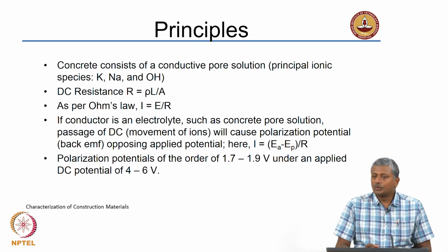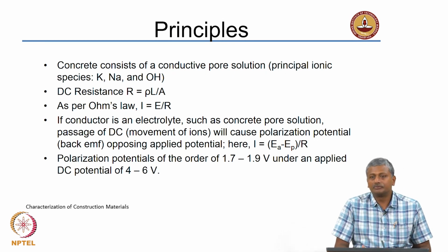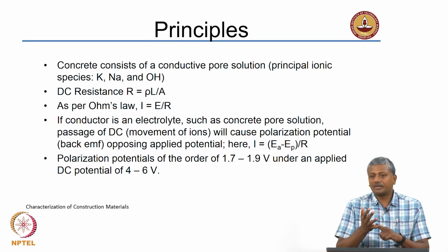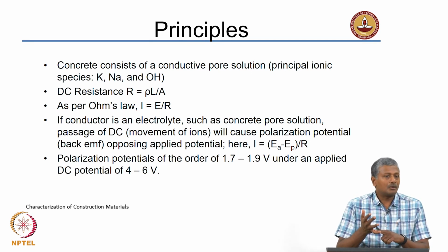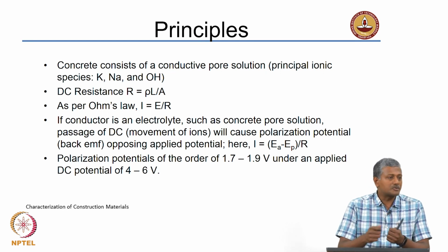Okay. Now, of course, you have learnt before that the presence of ions in a liquid will tend to increase the conductivity or charge carrying capacity of the liquid, right. So, if you study the electrical properties of concrete, it will give an indication first of the ionic strength in your pore solution, and second on how connected your pore solution or pore network is, because concrete itself is an insulating material. The solid phase in concrete does not transmit charge, right. It is only the pore structure, interconnected porosity that can transmit the charge.